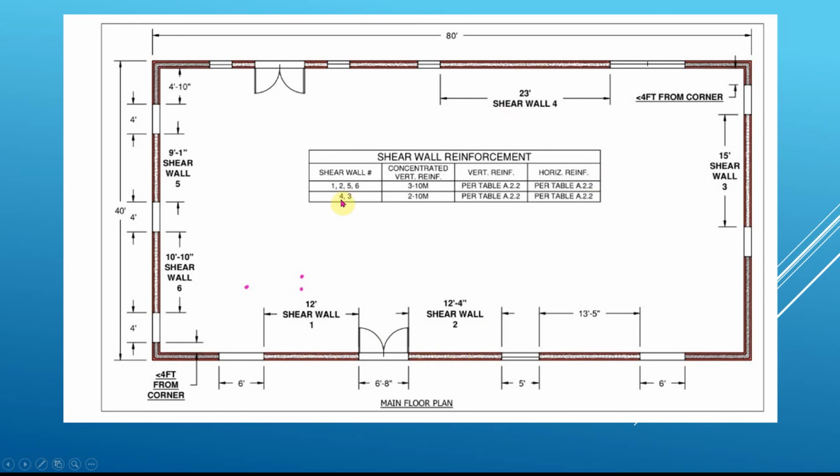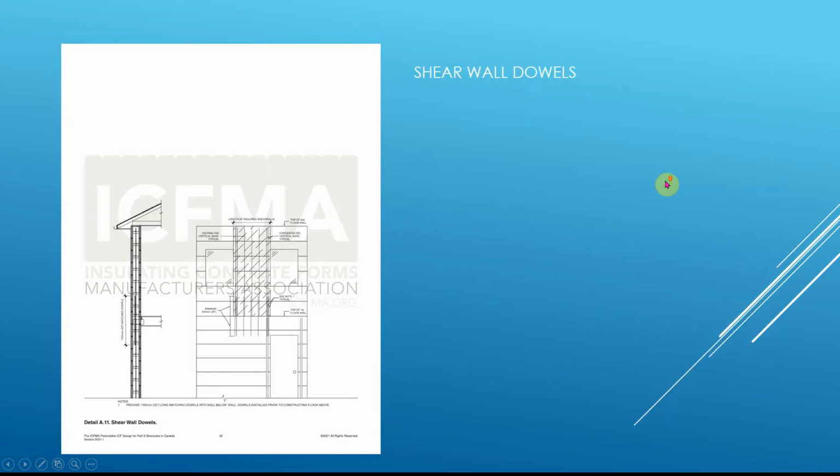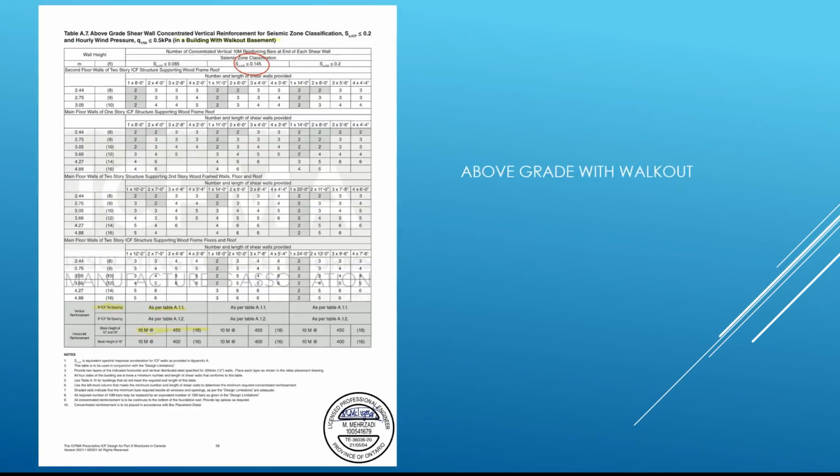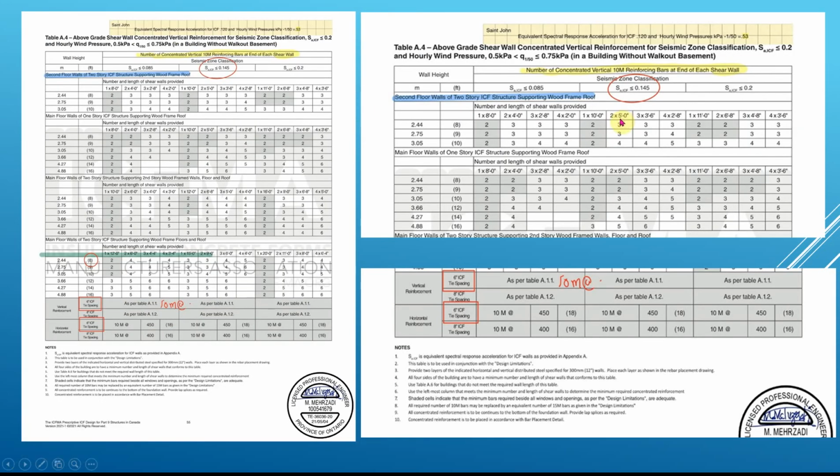You can see here that shear wall 4 and 3 are, oh, 3. So they got a 15-foot there. Again, what they're trying to tell you here is that you can take those, and as long as you can get the puzzle pieces to fit on that wall right there, you'll be good. So if we go back up here again, just to get you rolling, in this wall here with the spectral, I could have had one 10-foot